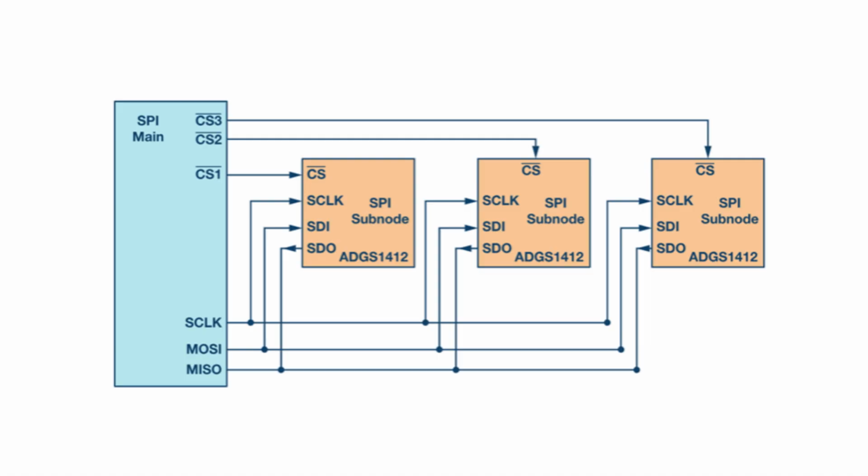If the master then wants to talk to slave #1, it pulls slave #1's CS line LOW, talks to it, and then pulls its CS line HIGH again. So it's like activating them one at a time using their dedicated enable line.